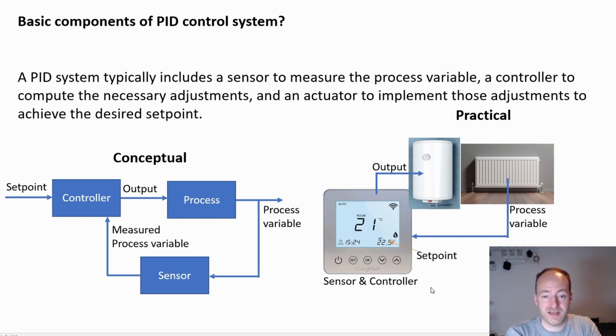Controlling all this is our control system. It looks something like this in my house. Basically, I enter a value of the temperature I want in the room. So for example, 22.5 degrees, that's my set point. In here, there's a thermocouple or something measuring the temperature, and basically it measures that value and it says, oh, hang on, that's below our set point.